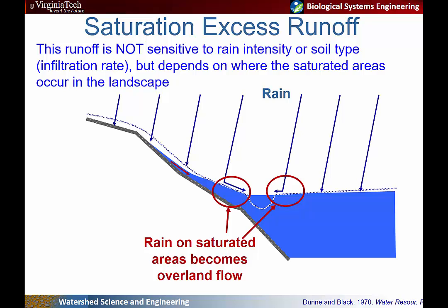interflow. When we talk about interflow, so rain that's infiltrated the soil up here flows down this hill slope, and once it hits that sort of saturated area or saturated edge, it can exfiltrate the soil profile. So you have infiltrate, which is movement into the soil profile. Exfiltrate is movement out of the soil profile. So we can get exfiltration of that water in these saturated areas of the landscape. So it's a little bit more complex of a process, a little bit more of a challenge to try to figure out where it's occurring in the landscape.